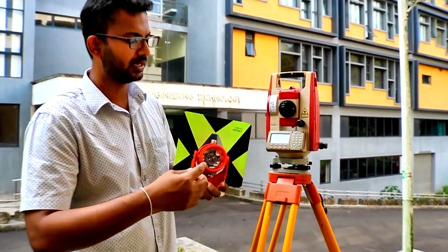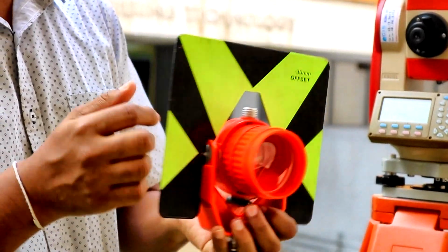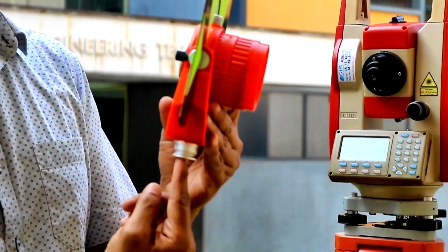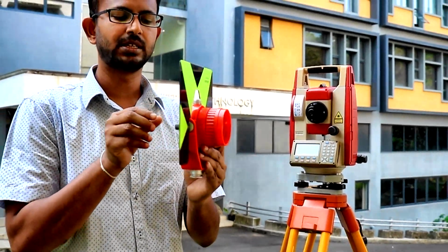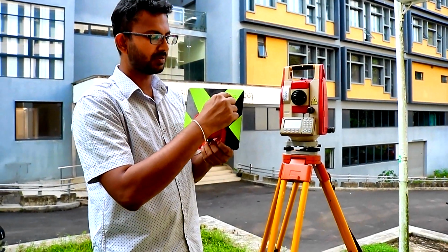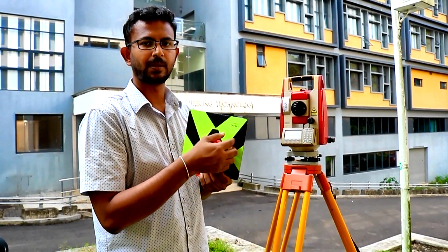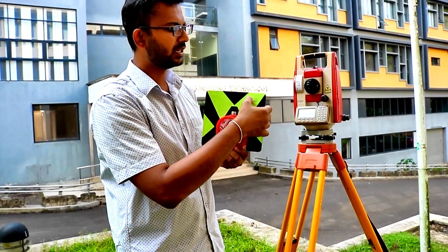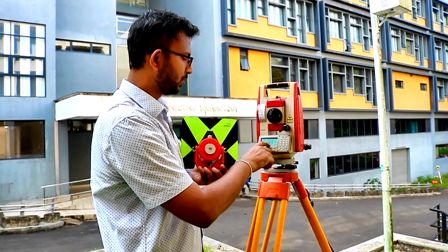It is minus 30. The meaning is whatever the effective center of this rays, somewhere 30 millimeters behind this pole axis. The pole axis is the exact point where we keep the prism, right? So it is just 30 millimeters behind this pole axis. Therefore that's why we feed it as minus 30. So whatever the reading we are getting, we need to deduct this minus 30 from the reading, right? Otherwise we will get a wrong distance, right? So we need to feed this minus 30. So now here the prism constant you don't need to change, right?